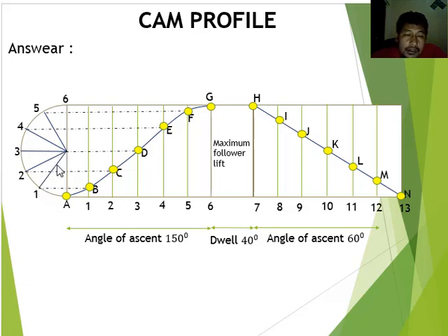For the first part, you strike a line to the right, connecting the number 1 to the cam motion. This is for the first point. This is point B. Point A is the beginning of the semicircle, the start point. B is the intersection of the first part between the semicircle part and the cam motion part.